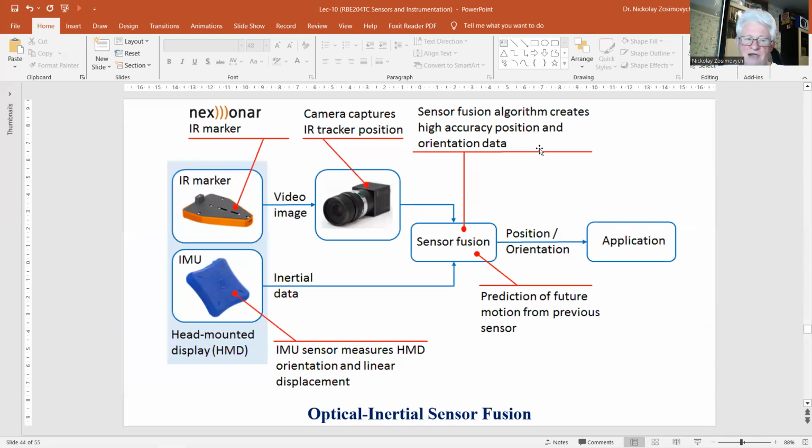Inertial-based sensors respond directly to acceleration, avoiding the noise-enhancing differentiation of position or velocity signal. Such an accelerometer comprises a mass and a spring element, see also piezoelectric sensor. When the mass is accelerated, the resulting inertial force causes the elastic element to deform in proportion to the applied acceleration.